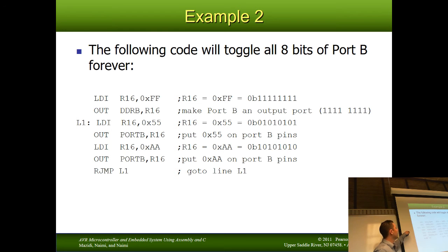All it's doing, each little step, is LDI then out, LDI then out, LDI then out, repeat. It's a fairly common code pattern that you'll see. Load into a register and then send out to an IO register. When we talk about macros next class, we're going to make this much easier to write.